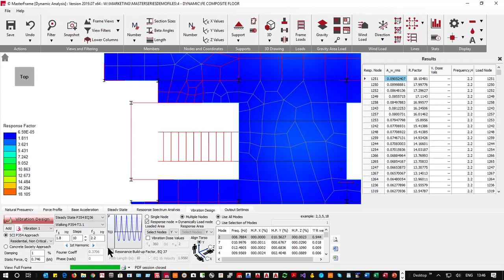So we're actually using a compounded set of vibrations all superimposed with each other to do this more realistic response factor. Because it's not the speed of the vibration that people get annoyed with, it's the acceleration. It's how fast they can detect it from the movement of their feet going up and down on the floor. It's not whether it's going up twice a minute or twice a second or 4 times a second. It is how fast and how far it goes.